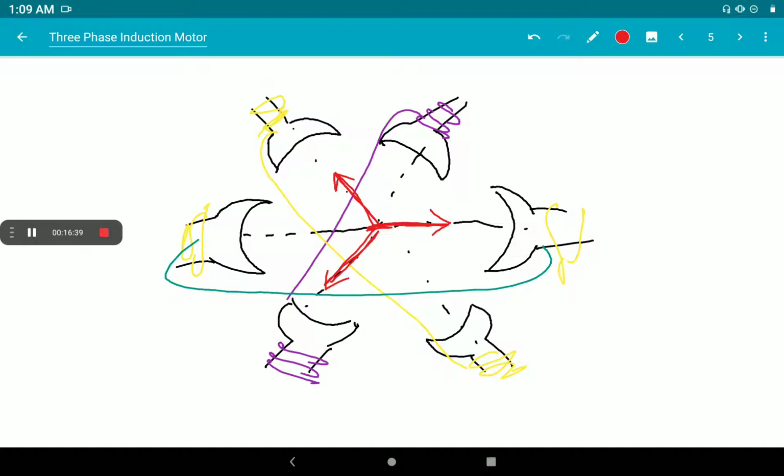Thereby, a current will flow through the rotor conductors, and by virtue of relative motion with respect to the field inside the machine, by Lenz's law, there is a force induced on these conductors, and this force on all the rotor conductors creates a torque, which makes the motor move.